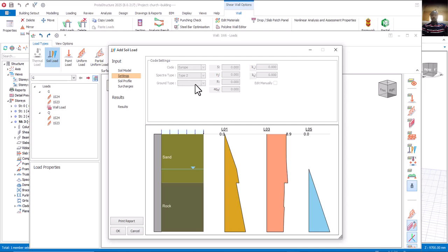On the ground type here, we are not going to be using anything, since our structure is not in an earthquake environment. Is that okay? Because the moment you pick any value here, automatically it will require us to input some information here. Is that okay? So that's why the software automatically closes it so that you do not enter anything. But the moment you know what you are doing and you know that what you need is earthquake or seismic design, then there's a place to check it so that you have access to this information here.